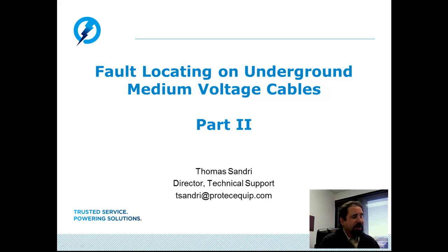In part 1, if you had gone ahead and attended or played that particular webinar, we covered the various fault locating techniques that are available to us today. We covered the capacitive discharge or thumping method, along with various forms of time domain reflectometry. Those included pulse echo, arc reflection, and impulse current reflection methodologies.